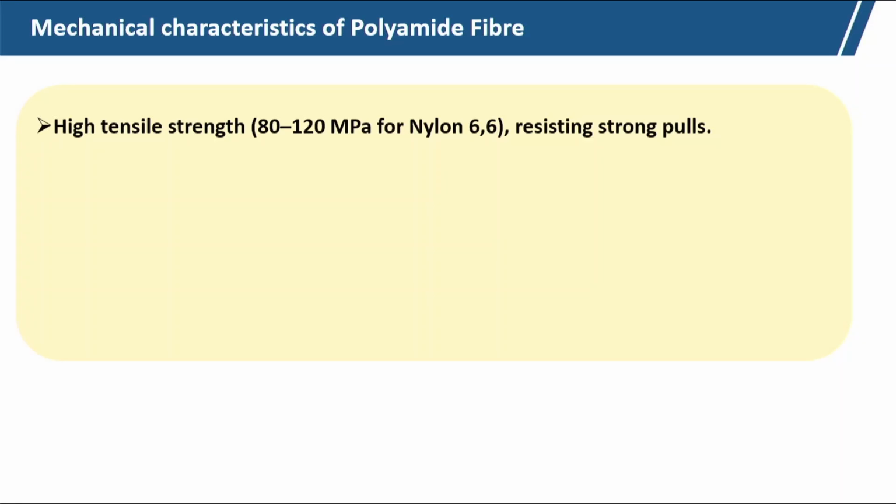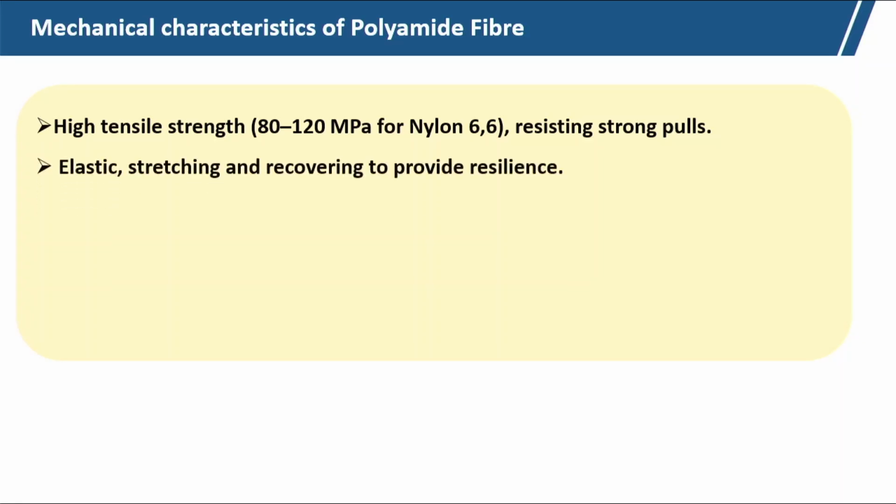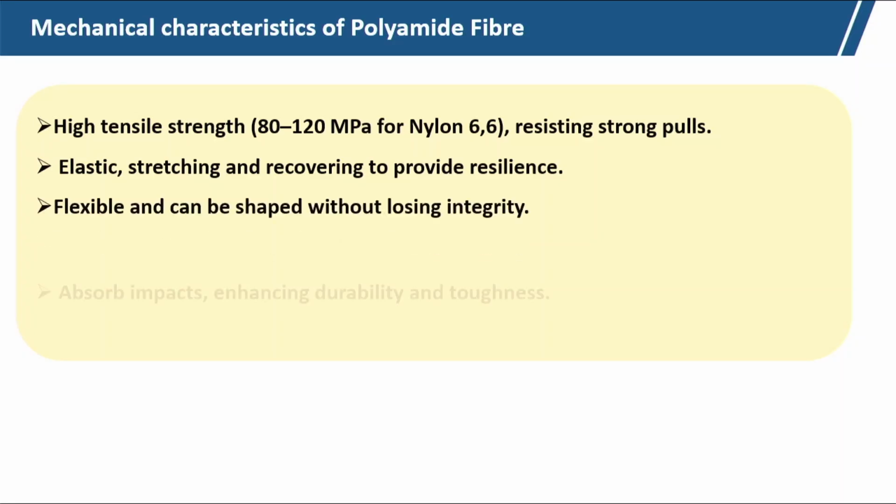And as far as mechanical strength is concerned, it has high tensile strength, 80 to 120 megapascal for nylon 66, resisting strong pull. So, this can be used for different ropes and all applications where high strength is required. Elastic stretching and recovery provide resilience. So, it shows some elastic characteristics, flexible and can be shaped without losing integrity.